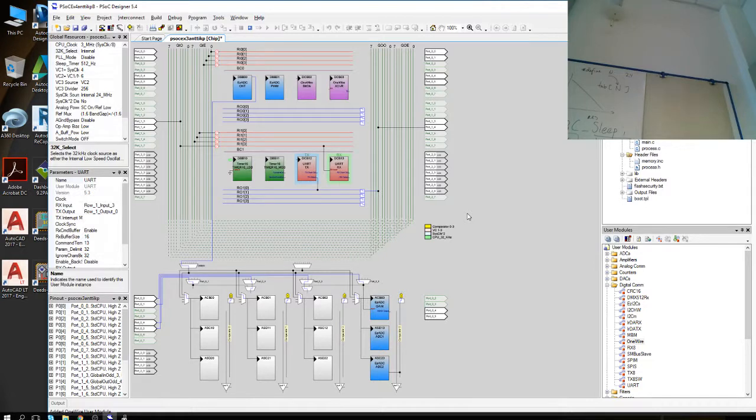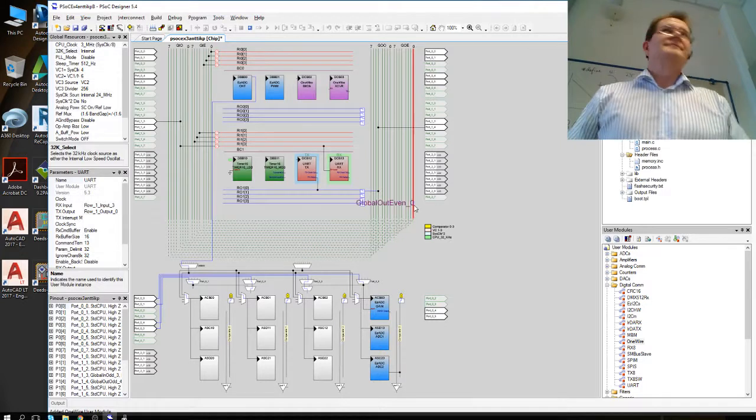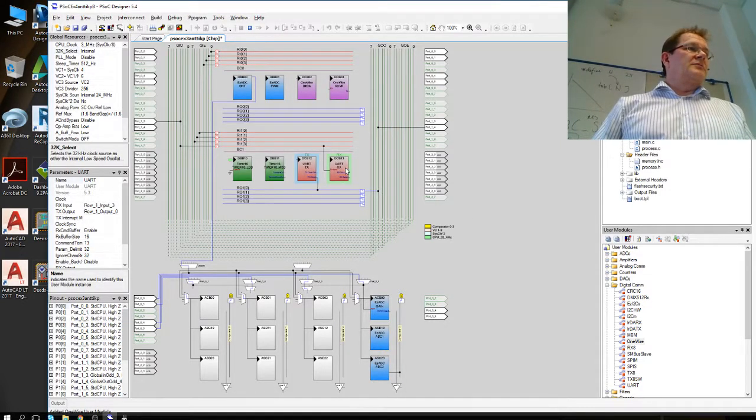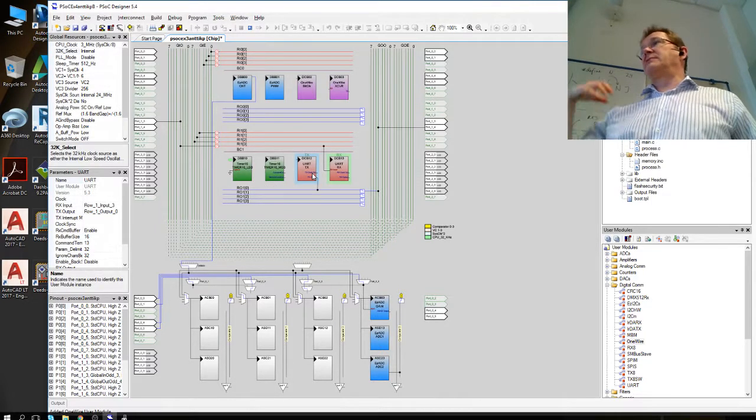Okay, so now we have receive and transmit there. The receive part also has the interrupt service routine. So again, you can make a hookup so that whenever there is a character coming, it gives an interrupt and you read what is the command. And transmit is very simple. You just give a transmit command.